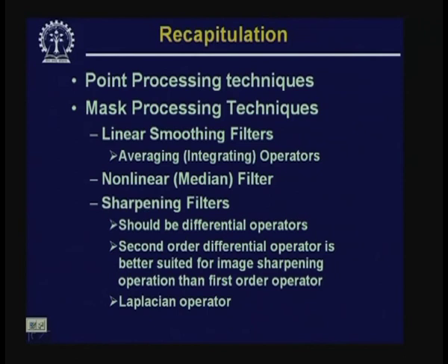We have also talked about a nonlinear filter based on order statistics, the median filter, and a sharpening filter, which is nothing but some sort of differential operator which differentiates the image pixels to sharpen the image.